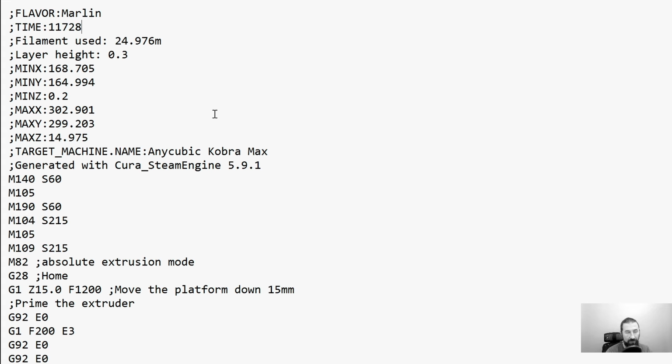This is actually not true, because about 90% of G-code which is used even in different flavors is actually the same. So, and flavor differences are mostly special commands, some special macros used by your machine, and these are usually not part of your actual toolpath. So normally your flavor differences are some kind of pre and post processing commands. So first of all, I will divide it into some sections.